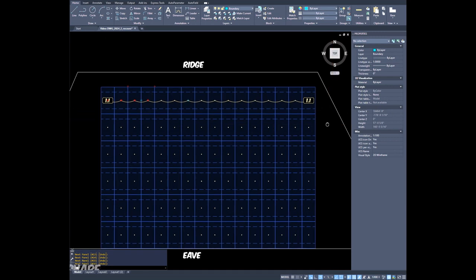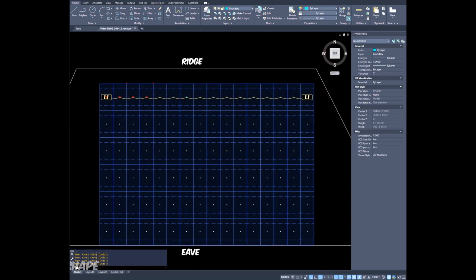And when you repeat the command, it will ask you for the inverter number and string number again, but for the inverter number, it's going to stay as 1. The string number is going to go up to the next one, so it's going to switch from 1 to 2, and then it'll keep the same string count, so it just remembers whatever the last string was that you put in, but you can always modify that by just entering whatever number at whatever value you want.